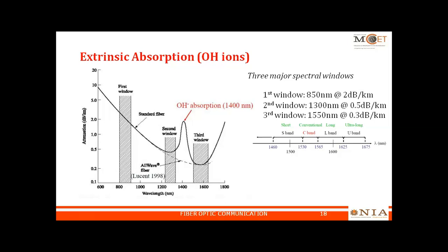So in unit number 2, till now we have discussed various attenuation mechanisms like absorption: intrinsic absorption, extrinsic absorption, atomic defects, then scattering losses, that is linear scattering as well as non-linear scattering, and macroscopic bending, microscopic bending as well as core cladding losses. These are the losses.